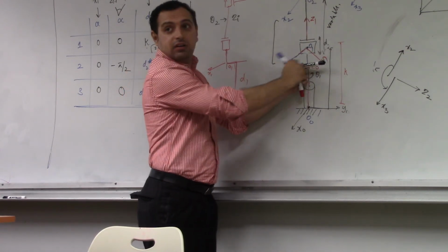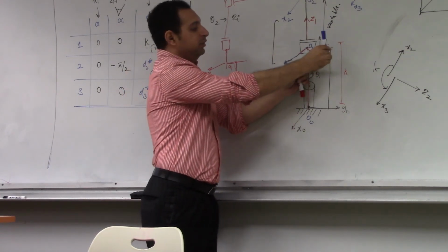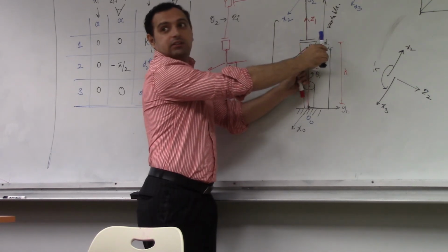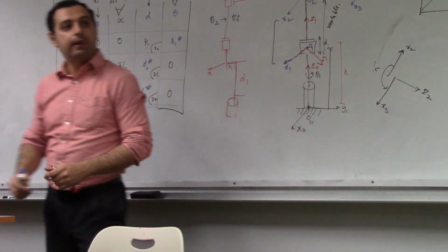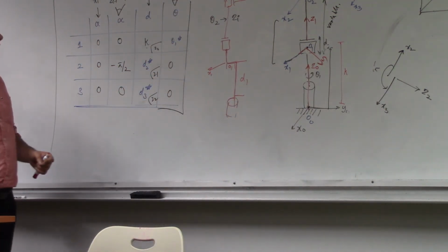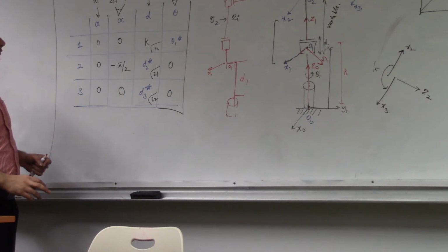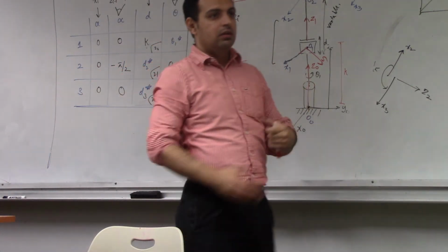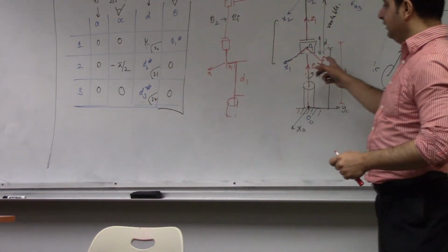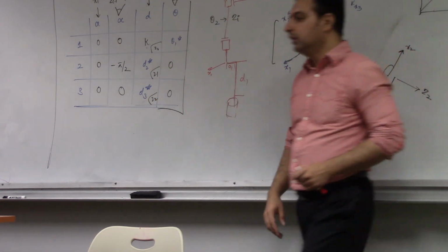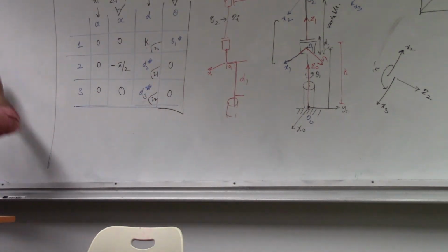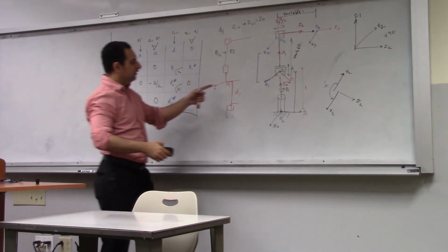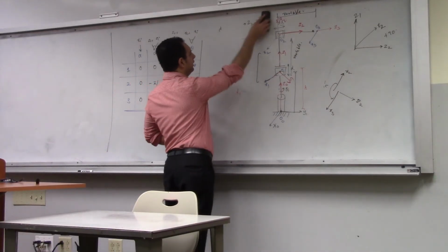So I'm measuring one distance along this. Something has to be measured along this axis, right? In which case, if I move this here, D becomes 0, A becomes 0. If I move this far away, A starts appearing, all right? So the A1 is, we said, instead of 0, we need to put A1, right? Here, okay, in case there is a displacement. Yes. So when we go to a SCARA manipulator, I'll give you other examples where you'll find it difficult to do it without having a displacement compensated for.